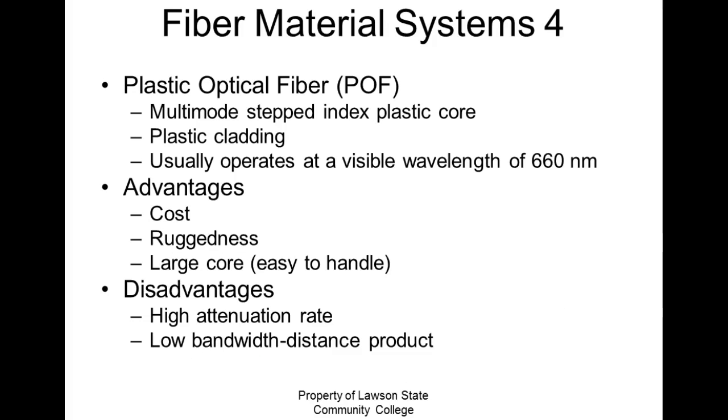Plastic optical fiber, multi-mode step index core, plastic cladding, usually operates at a visible wavelength of 660 nanometers. Of course, the advantages of plastic are its cost, it's rugged, it has a large core, and very simple splicing. You can cleave or cut it with just an X-Acto knife. Then you sand it down to get that perpendicular surface. Real easy to work with. The end electronics is very cheap. So I'll show y'all some standard end electronics for plastic here in a minute.